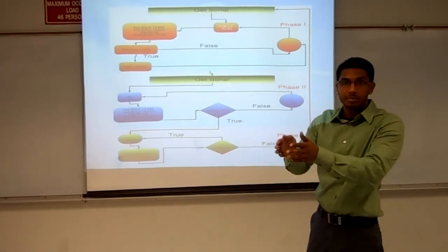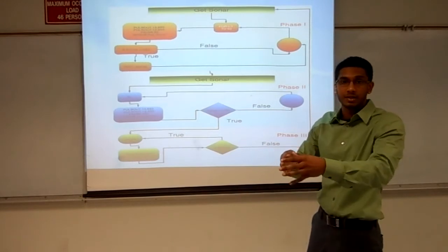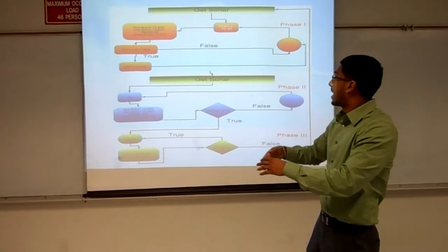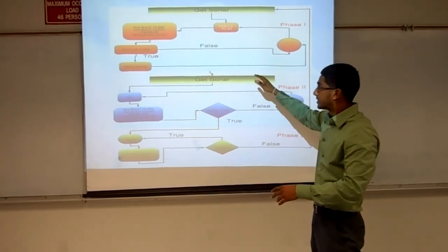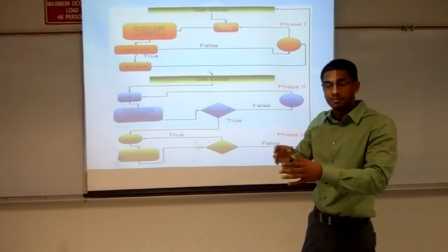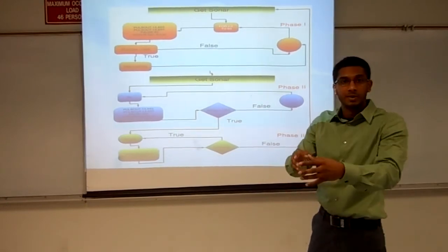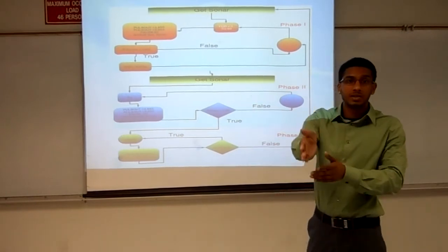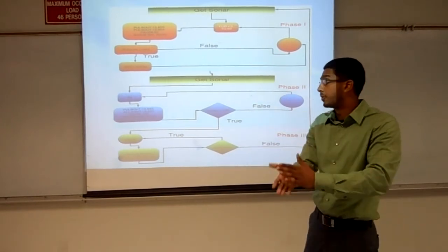From then, it kept going and it saved the sonar reading if the new sonar reading was higher than the old one. Once it got the sonar reading, it went to the second phase, which was to rotate the opposite direction and find that sonar reading again. Once the values matched, it went to the third phase, which moved forward to the object and stopped 2 inches before it.